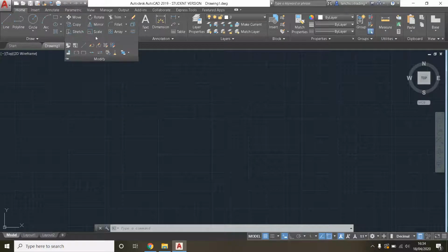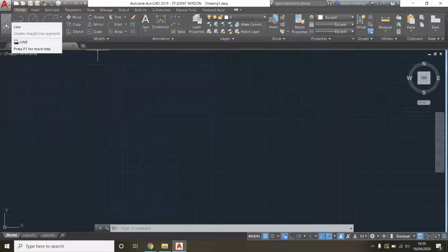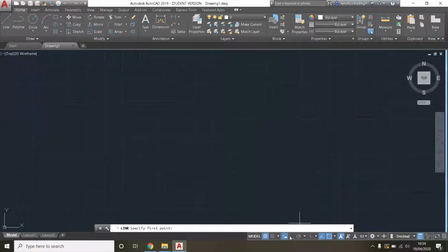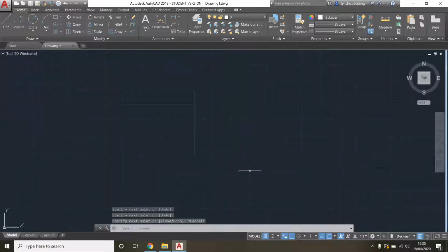All right. So how do we use our modify tools? The modify tools basically modify everything. This corner here, it's the basics. For example, if we click on line, in the previous videos, I spoke a lot about auto mode. This button right here makes us draw only in straight lines. Watch it. And you press the button escape to end your tool.